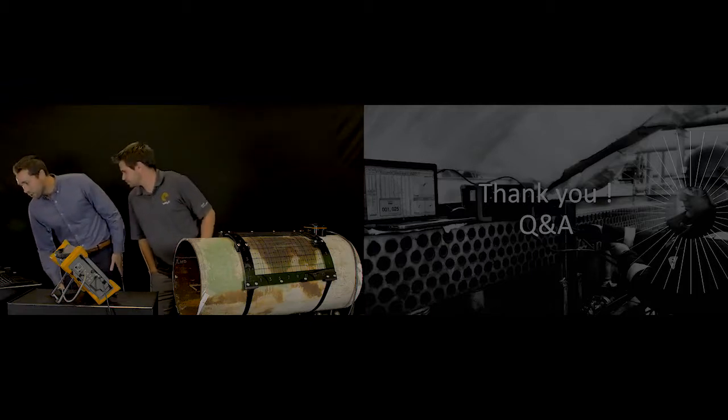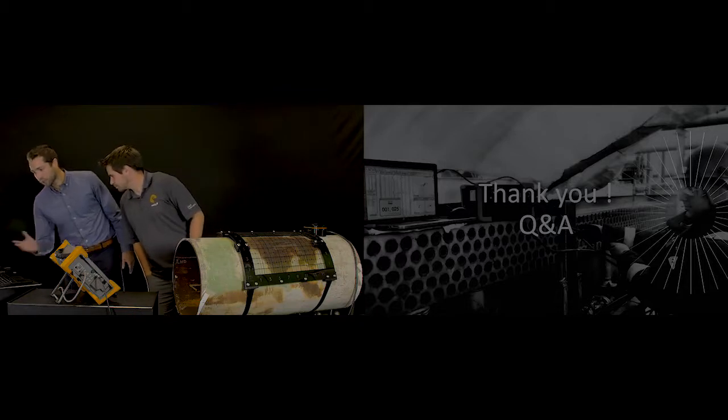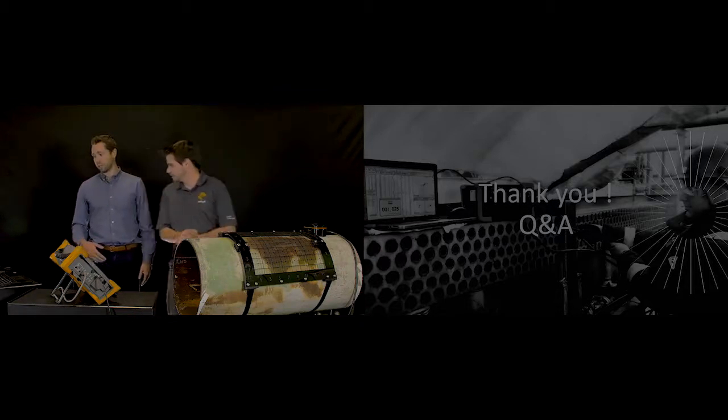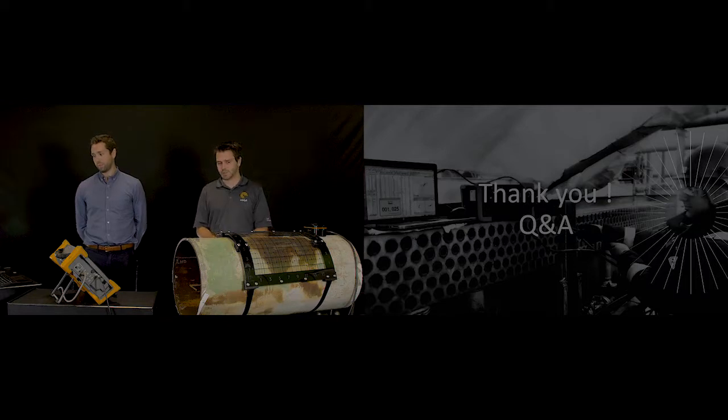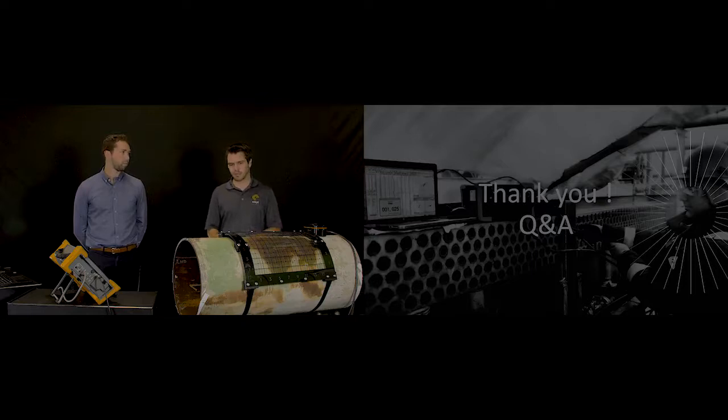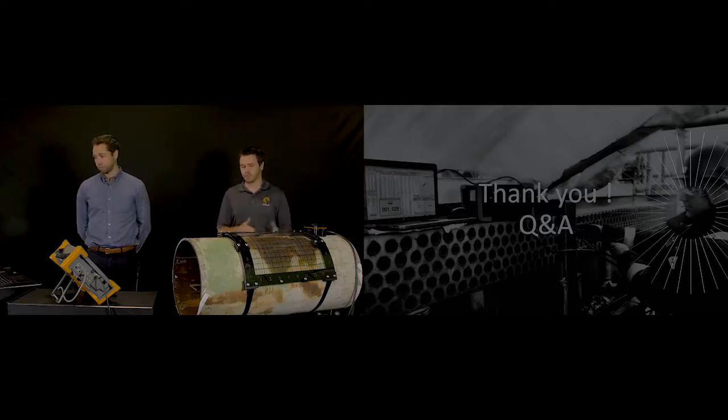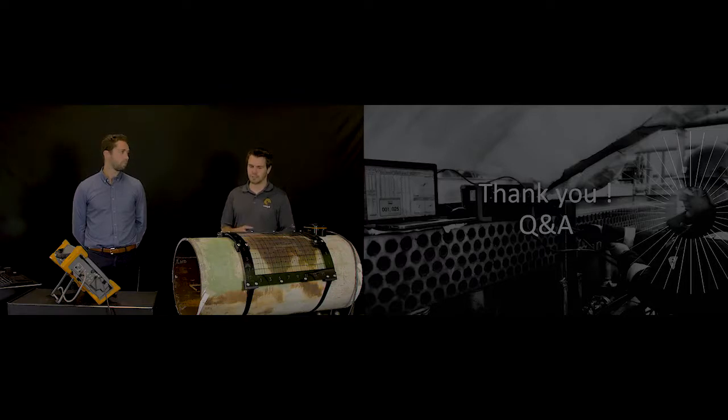Can you use the probe on composite wrap repairs? Well, we want this probe for now to be dedicated to scab corrosion. This is the application for which we qualified the probe. It's more sensitive to everything, including small defects and also change in material properties. So for now, we reserve it for scab assessment, but the inspection of composite wrap repairs is something that we want to introduce as a new functionality for this probe in the near future.